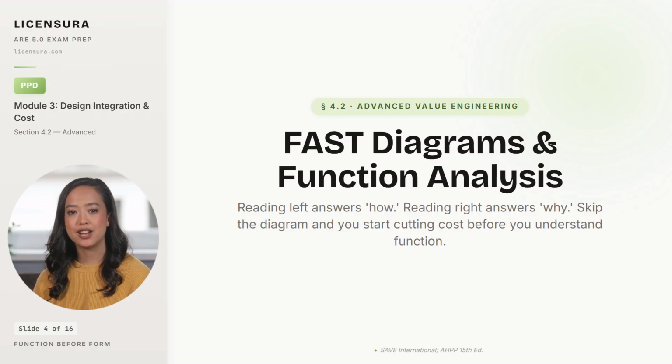Walk into a value engineering session without a function analysis, and the conversation collapses into a list of items somebody wants to cheapen. Most architects who get sued over VE decisions made that mistake. They accepted a cost cut without verifying that the function survived. FAST stands for Function Analysis System Technique, and it forces the team to map what each building component actually does before anyone proposes a substitute.